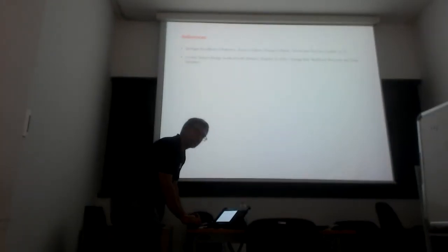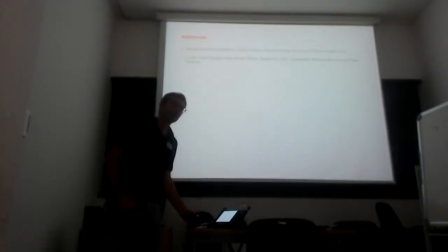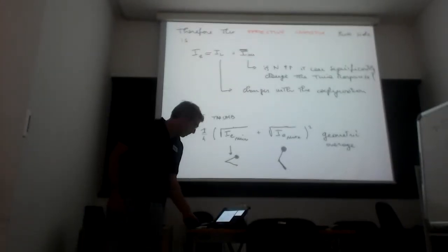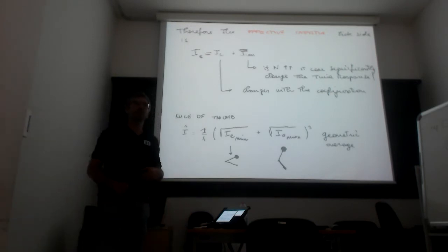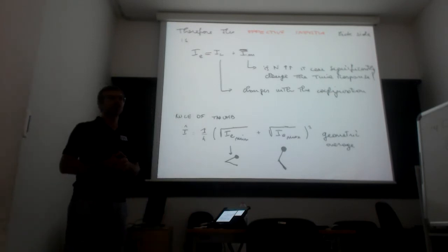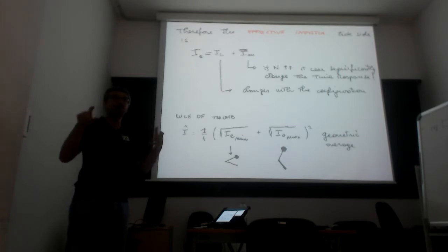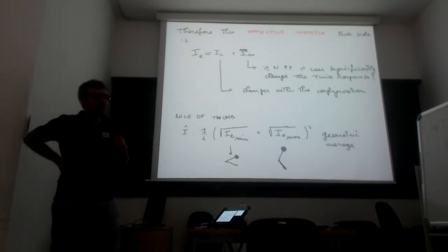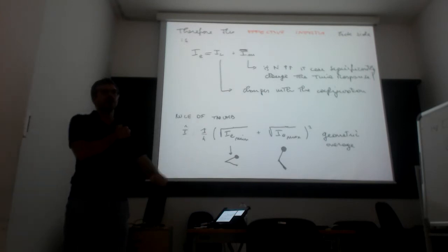I'm sorry, could you repeat where that averaging is used? Whenever you want to design a controller, let's say a decentralized one, and tune the PD gains, you don't want a single number for the inertia, so you need to decide on an average number, since your leg inertia is changing. If I want to tune the PD gains for this joint, we said we need to know the inertia from CAD, and then we set Kp and Kd to have critical damping.